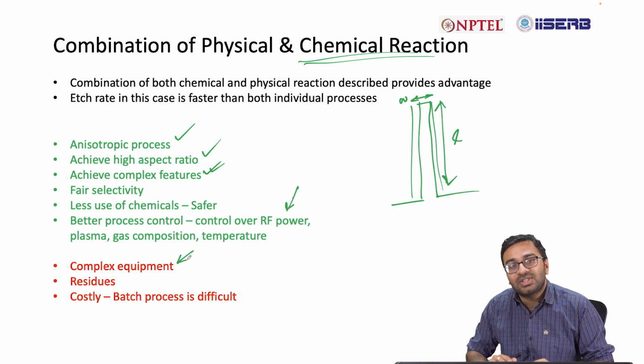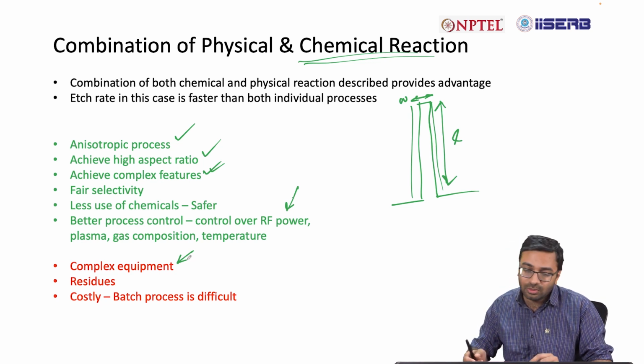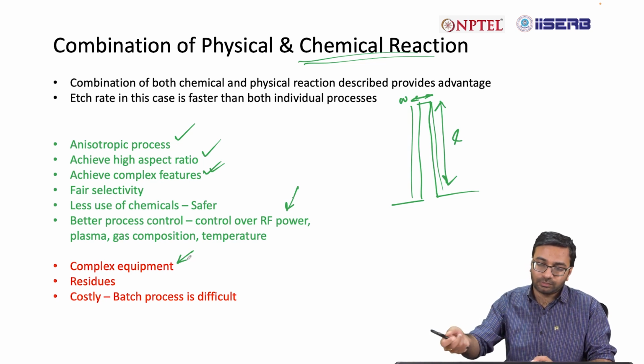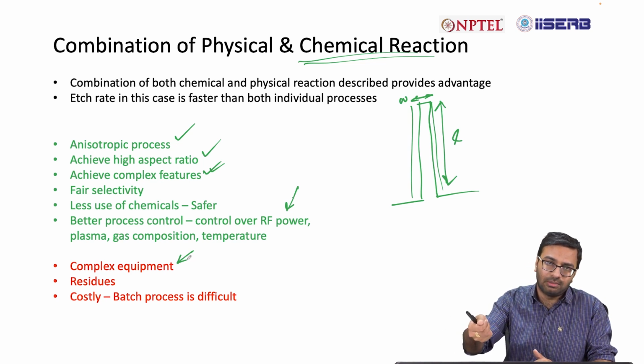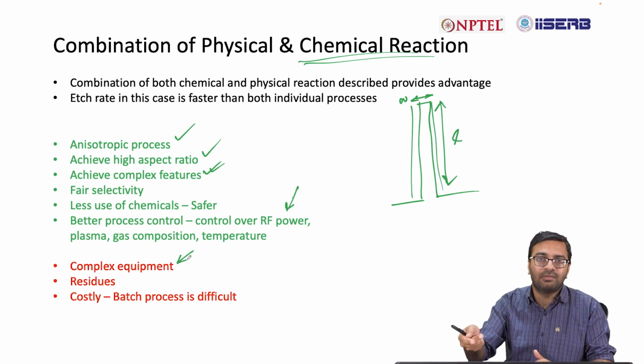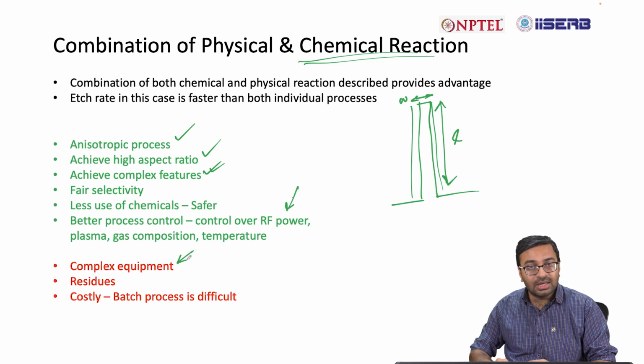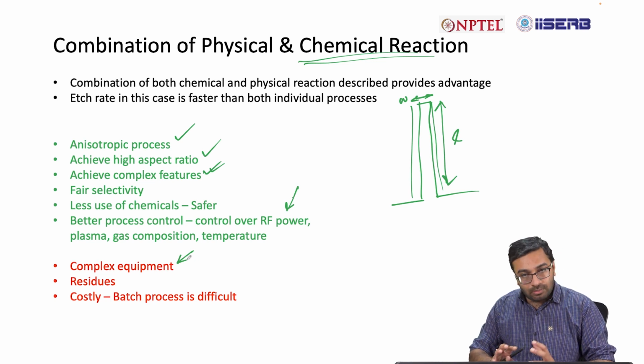However, in case of wet etching, it's a chemical based process. So you just need some container and a suitable chemical agent. Then you can put the substrate or the thin film with substrate inside the chemical. In dry etching, it creates a lot of residues, just like other plasma processes. There is a chance of contamination to some extent, but if you can maintain the gas outlets properly, that should not be an issue, but there is a chance.